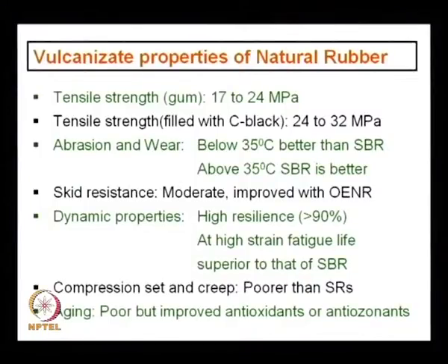So, how it fails means it fails after initiation of a crack followed by crack propagation. Okay. Now, these rubbers are having properties like some rubbers are having resistance to crack initiation, but once a crack is initiated, crack propagates faster. There are some polymers where it does not resist crack initiation. Crack may be initiated, but crack propagation rate is slower. So, these properties are available with, say for example, natural rubber and SBR, they are having just opposite properties, these two. So, this way it is the duty of the compounder to select a suitable rubber in his formulation while he is making a tire.